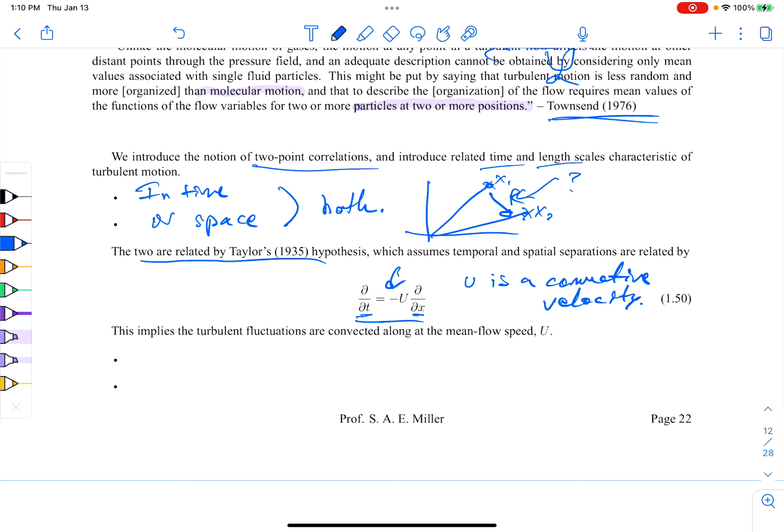He said, well, measurements show that in a jet flow, they move at different speeds depending on the radial location of your turbulent jet. And so a lot of people say, oh, the turbulent convection speed is like 70% in a jet as a first order approximation. And for higher order approximations, you can say it varies with position. It could vary between 40 and 70%. Or you can even do it on a wave number basis and show that different scales of turbulence are convecting in the flow at different speeds. So this is kind of like your zeroth order approximation. It works really well.